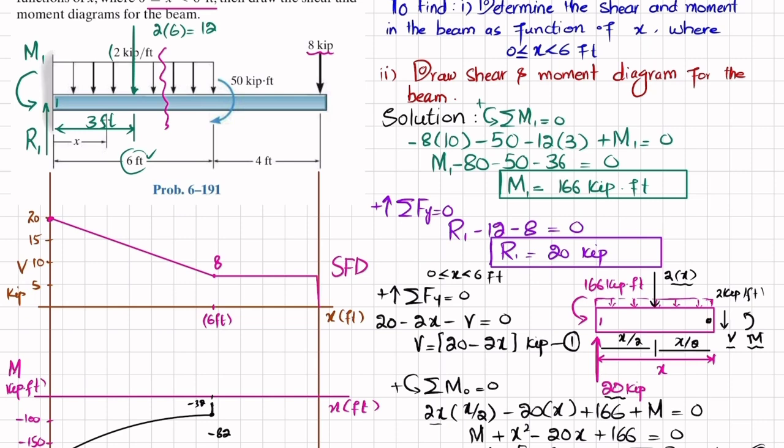And the last one is the area under the shear force diagram, and you can see this area is, this height is 8 multiplied by length 4. So 8 fours are 32. So minus 32 plus 32 will equal 0 at this point. So you will get the bending moment 0 at this point. And we will join these 2 points using a straight line here, and that will be your bending moment diagram, which is the answer of our second part.